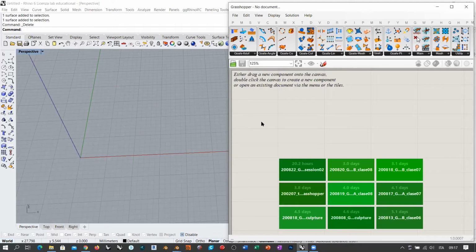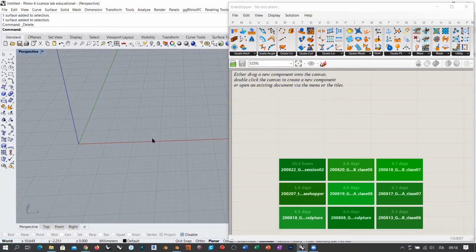So the first thing that we're going to do is define some mesh. Of course, you can start with any body, any surface or polysurface in Rhino, import it into Grasshopper and convert it into a mesh. But there are some limitations. It is always better to control mesh topology so that Kangaroo calculation and system behavior is a little more under control.